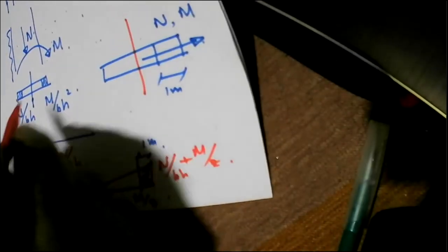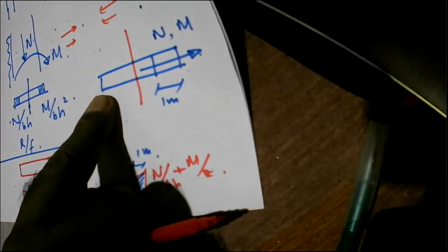But generally when you are doing this, you will not go beyond the midpoint, because when the wind is acting this way, the wind can act this way also. So there's no point in detailing the wall on this side, because when the wind reverses, what has happened here will happen on this side. So what we do is we'll do the calculations only up to the midpoint and select the reinforcement requirement in the wall.